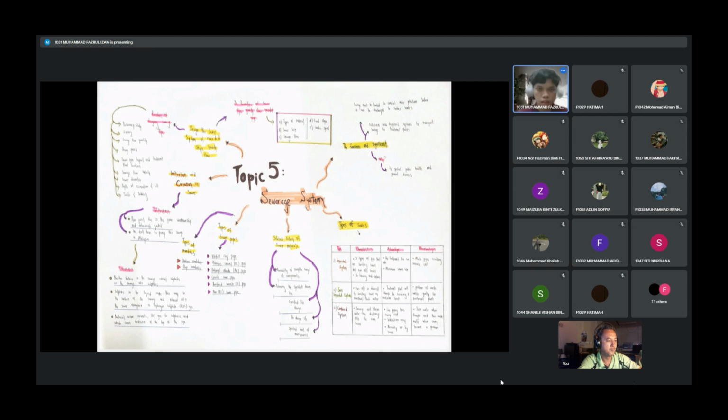There are 4 types: the shallow type, deep, shallow, and the backdrop manholes, and the backdrop manhole with internal outlet pipe. And then we will see the infiltration in sewer pipe and the reason of corrosion in sewer pipe. Next, we will move on to the next subtopic, which is called design the sewer system of rounded shaped gravity flow. In this subtopic, we will learn about the procedure of designing sewage pipe and the parameters of sewer pipe